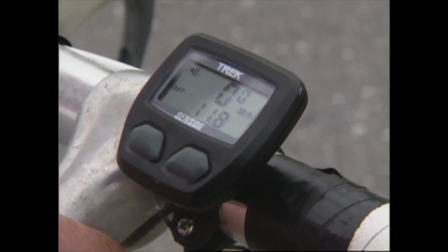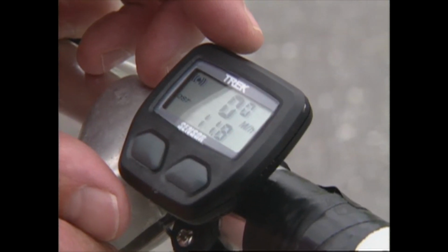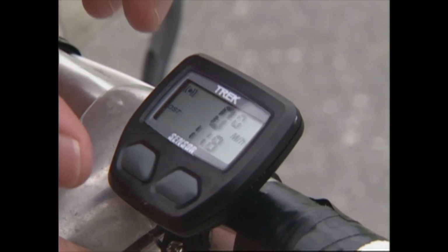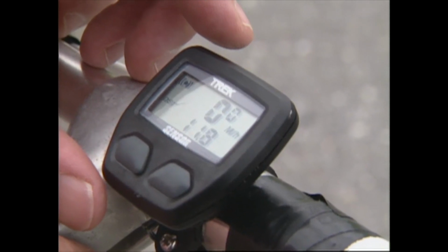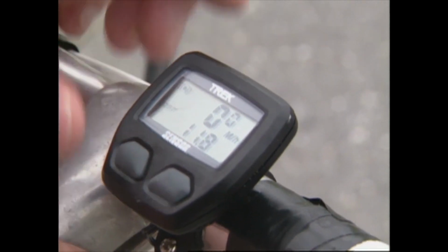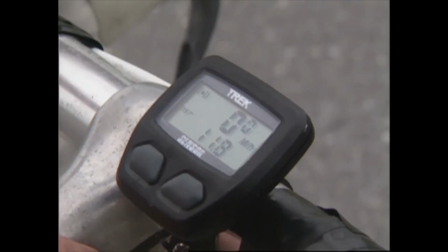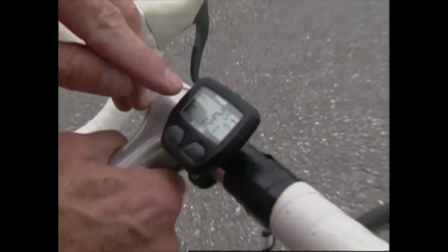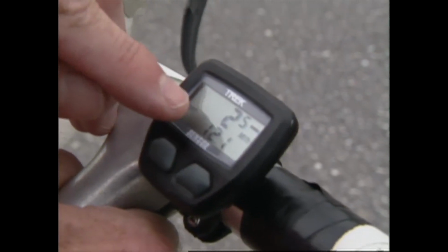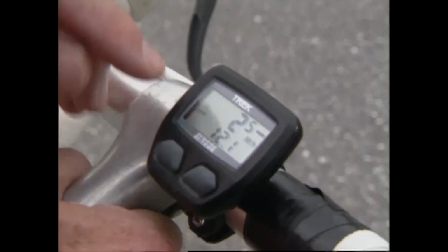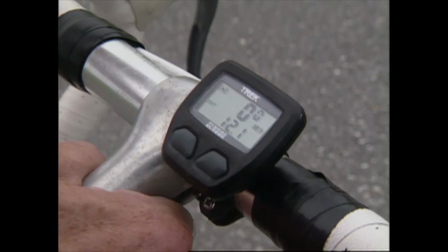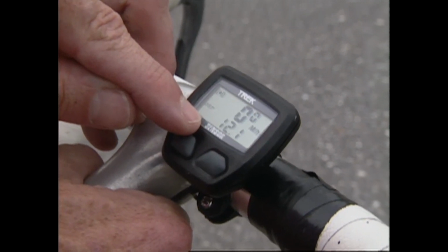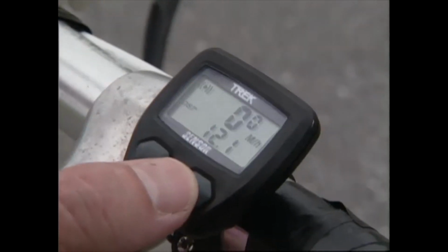Now, the computer unit has a quartz clock in it, and the quartz clock essentially counts the number of pulses per second. If I know the circumference of the wheel, I can figure out what the velocity is. So for example, if I spin the wheel, you can see that there's an indication of pulses here, and I get an indication of velocity. I can also integrate the number of pulses, and I can get a total distance covered. In fact, on this ride, I've gone about 12.1 miles. I can accumulate that over time.